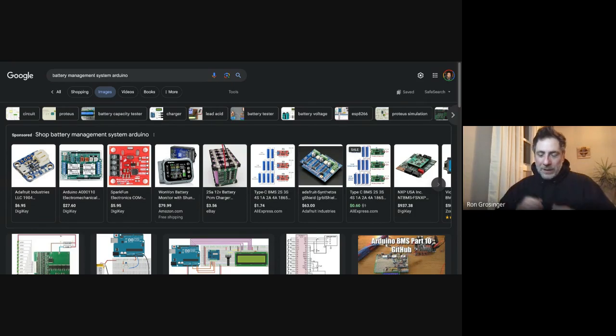This is obviously not lithium, but this would be like an alkaline battery example. Well, if one of them hits the top, and the other one's still at 1.4 because you only moved up a little bit, now you have a situation where you have actually not fully charged the pack.